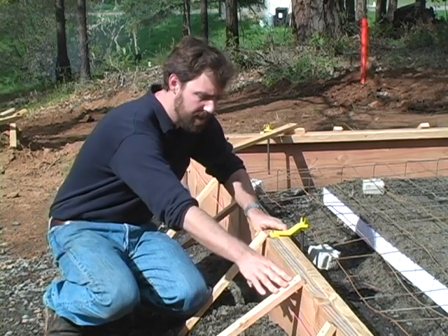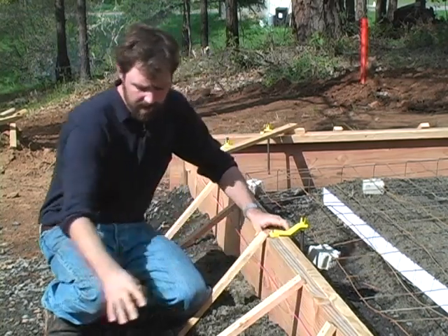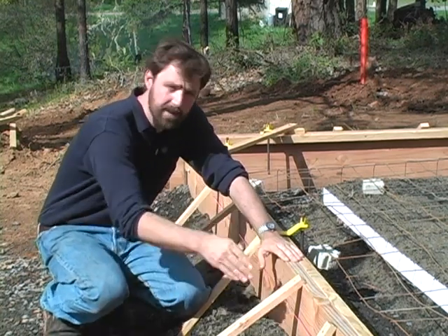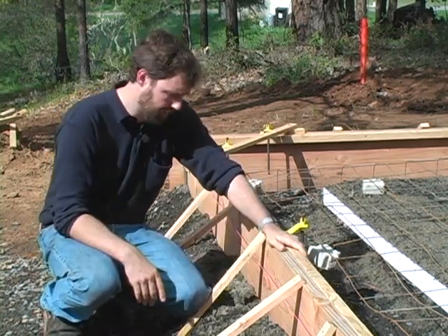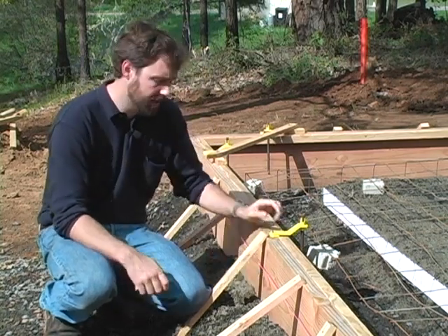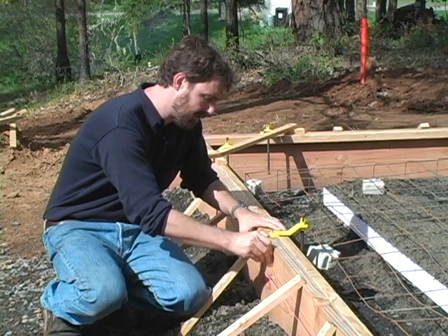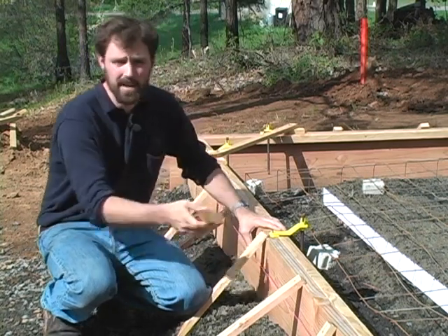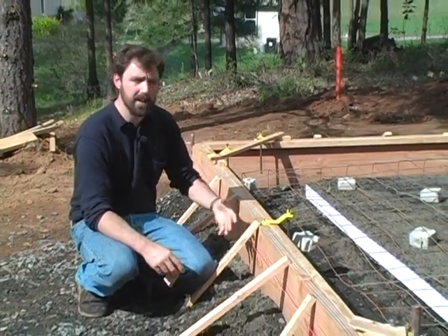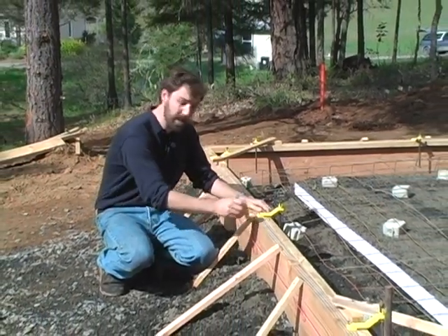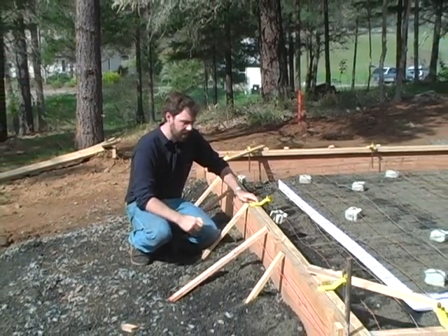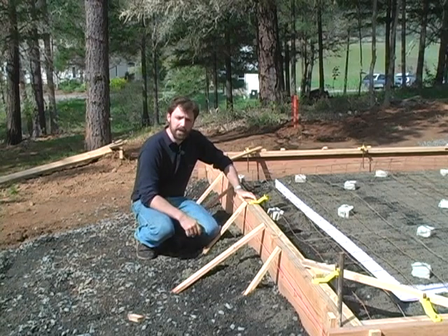Now, I've got this wall braced off pretty significantly. It's a little bit of a drop here, so to get a stake deep enough into the ground, I wanted to make sure that I had enough of these so that the wall didn't bow out with the weight of the concrete. Another thing I've done is I've left a dry line or a string line on here so I can come back with my block of wood like we did to set this in place and check it as the pour takes place. So if we do have an instance where one of these fails or gives way a little bit and we get a little bow in the wall, we can check it and move it back into place and re-brace it at the time when we're pouring. So it's just another way to be able to check the wall and make sure we end up with a straight wall.